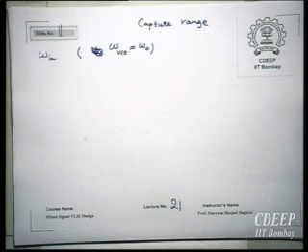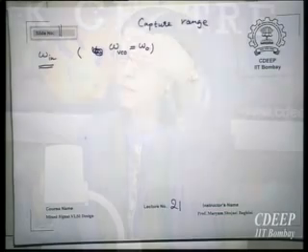Now, what will happen? Loop is not locked, but anyway, it's working. I have a frequency of omega in. At the input of phase frequency detector, I have another frequency. What is that second frequency value? Free running frequency, exactly. So you are giving two frequencies to a multiplier.